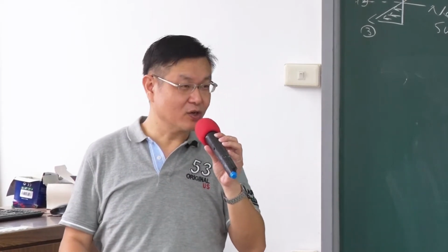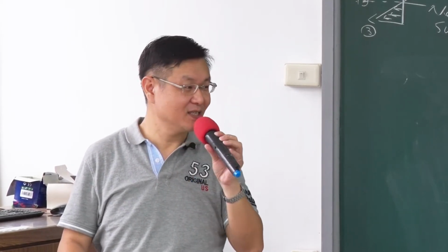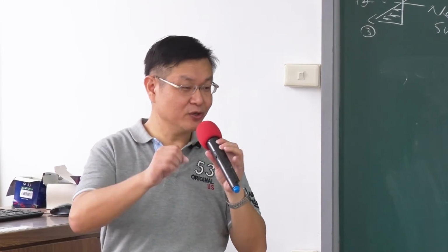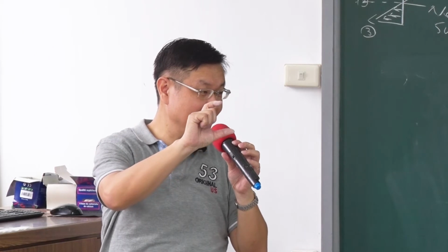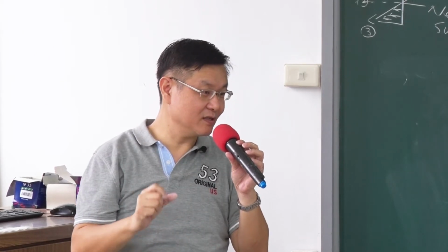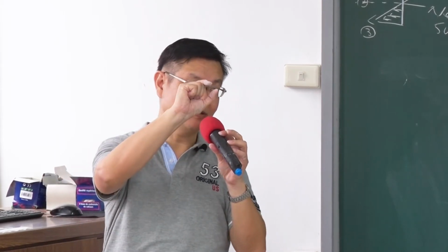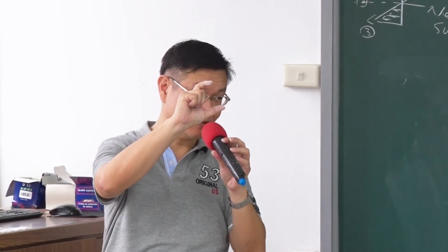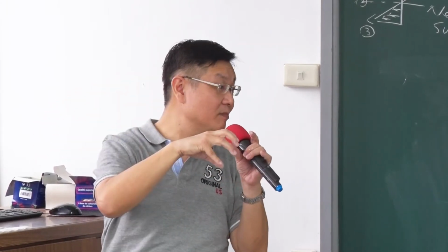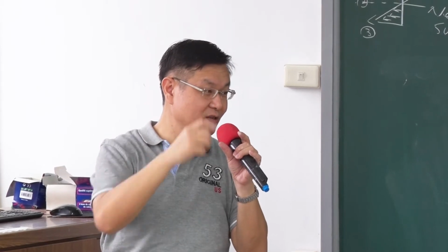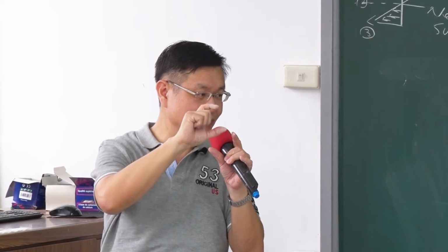One example is cork. Do you know cork? 软木塞. When you drink red wine, you see there's a cork on top of the bottle. That kind of material has a zero Poisson ratio. When you push it down, it never expands, right? It's important when you push the cork into the bottle. If it expanded too much, it would give a lot of pressure inside. So you want to keep the same structure on the top and the bottom.